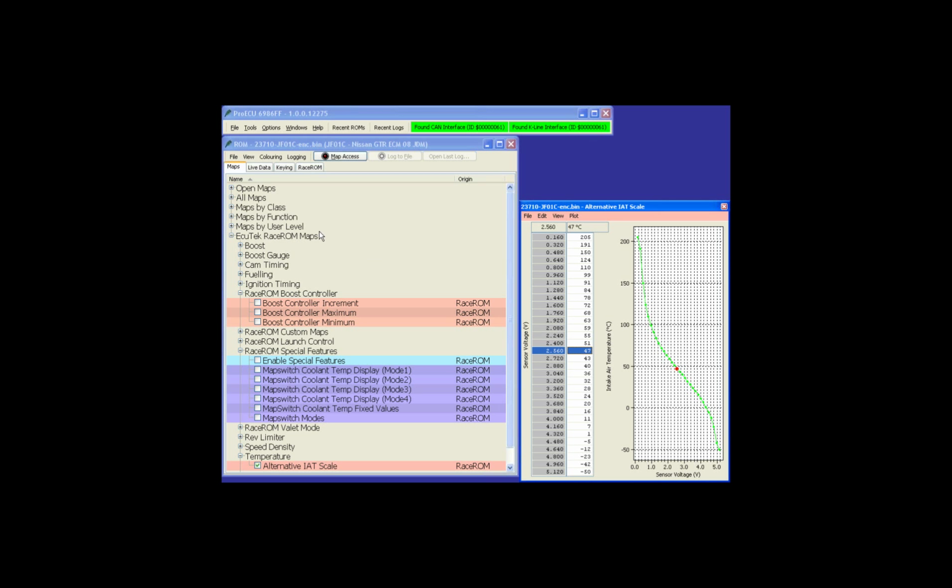So when we are running the car in real time and we adjust the boost target up and down using the cruise control, the boost control will be the final amount. Just because we can go up to 1.5 bar doesn't mean we're going to get 1.5 bar. The maximum will still be dictated by other maps, like compensation maps for temperature and altitude, compensation maps for air temp, and also the profile of the target boost map itself.